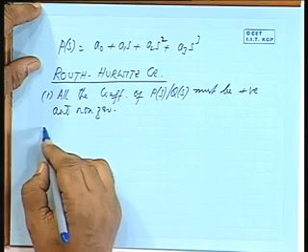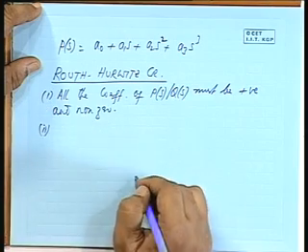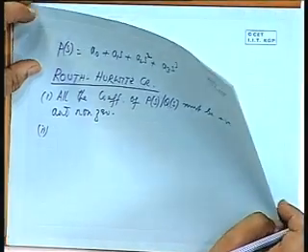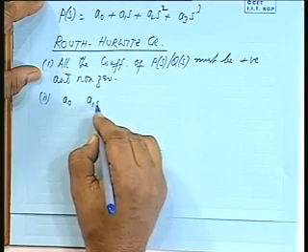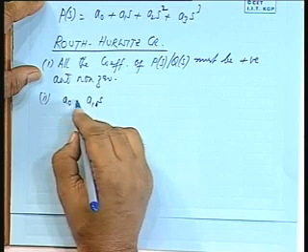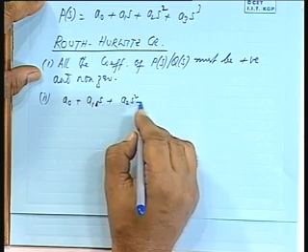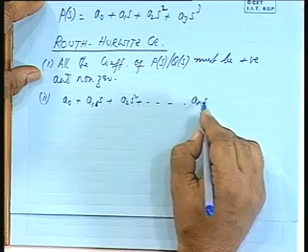And the second criterion is you make a table, a Routh array, and from the first column you can see the positiveness of those terms and decide whether it is a stable or unstable system, that is, whether all the roots are in the left half plane or right half plane. So let us write the table. Suppose you have a0, a1 s plus a2 s squared, etc., as the polynomial up to an s to the power n.